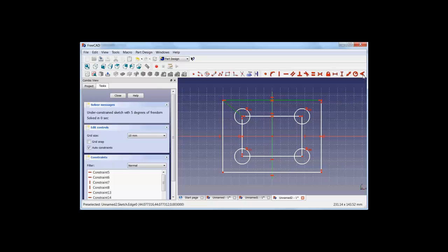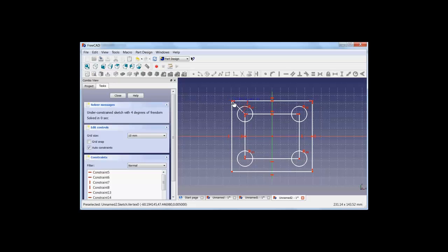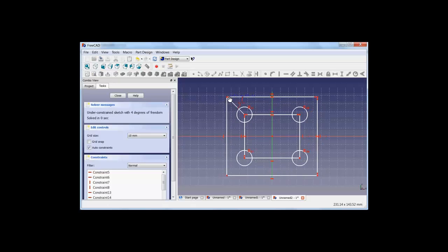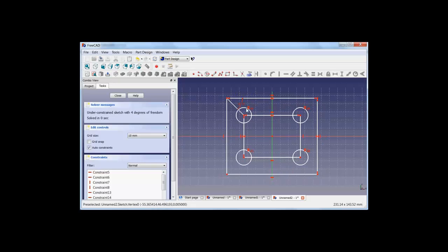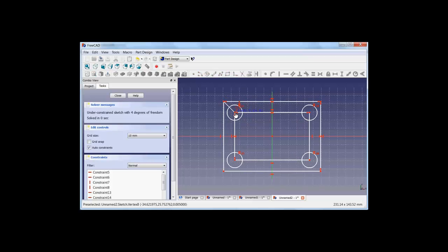And this angle should then be, I'm sorry, I was moving it. This angle should then be 45 degrees. Here we have a fixed angle of a line. So here we have 45 degrees, and you might remember from math that then the distance is the same as this distance. So as I change it now, the holes always have the same amount of flesh, so to say, to the side.